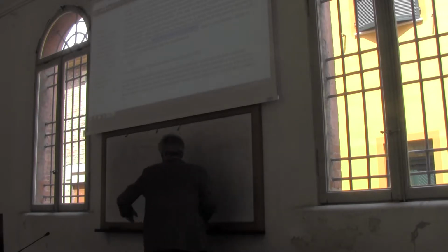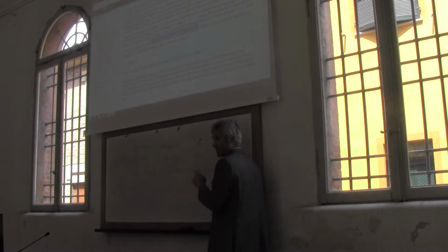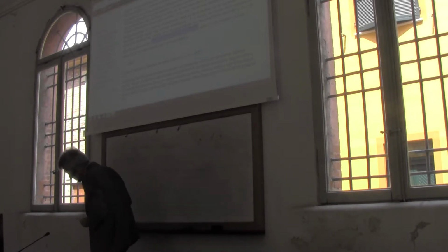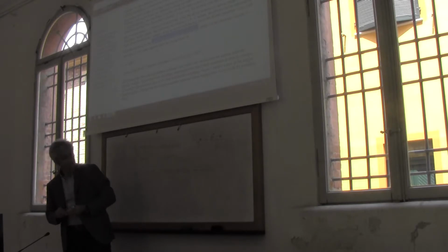Sorry, I said Re and I wrote Rf, Re star, which is equal to the product of something that is indicated with u star, which we will describe later, times d, we know what it is, divided by the kinematic viscosity of water. Let me see that the symbols are the same.